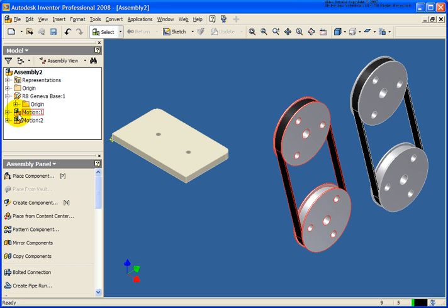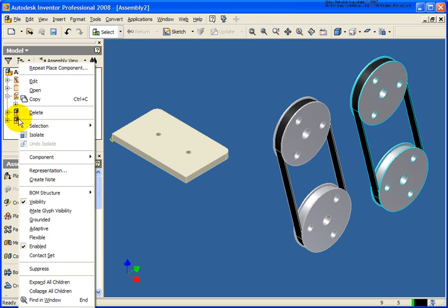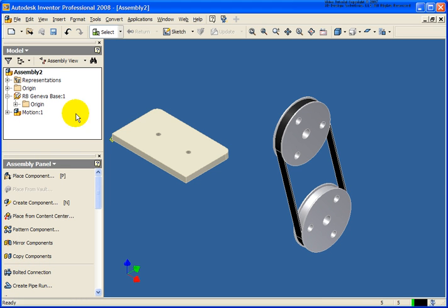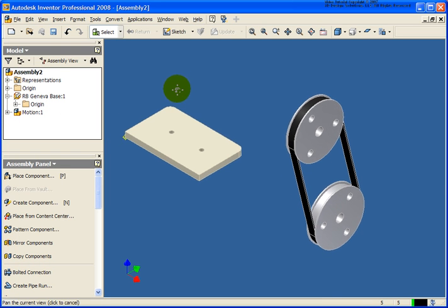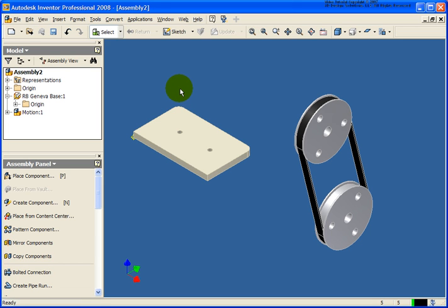In this case, you'll see that there's 3 blocks representing that. In this case, it's showing me that that's the assembly. And by expanding that, you can see that I now have 3 individual components that are nested inside there. So again, I'm just going to delete motion 2 because I don't need that, just like we did before. So that's all there really is to placing existing components into an assembly file.